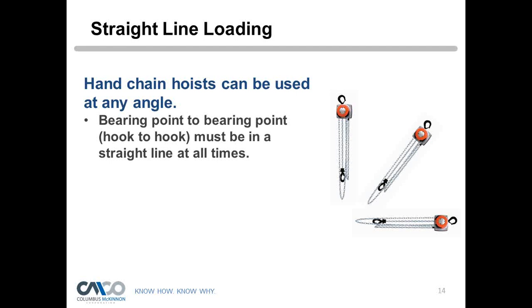So any of those configurations there, as long as your connection points are proper, you can do that. But you need to know some things before you do that. You've got to be safe before you do it. So once you've done your pre-operational inspection and you deem the hoist as safe, you need to know more things. How much weight are you lifting? That's very important. Where's my center of gravity? What's my share of load on the lift points? And then from there I can figure out my tensions.